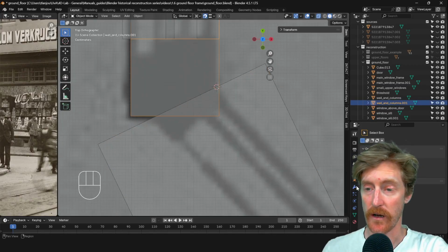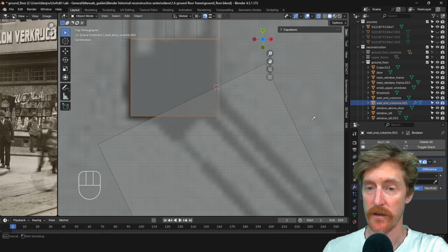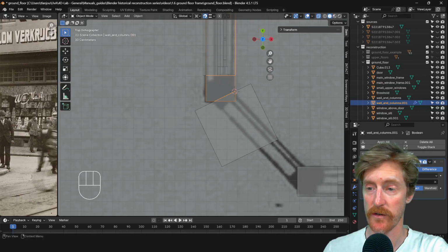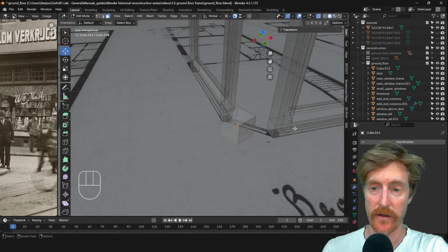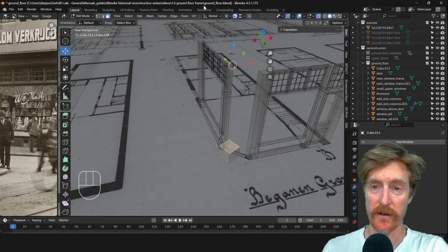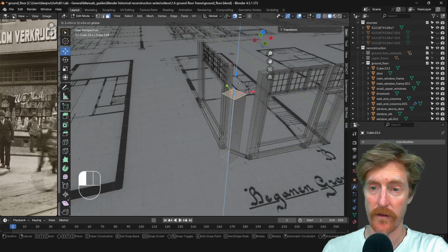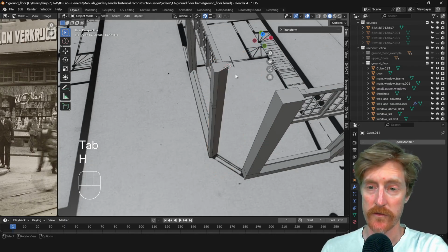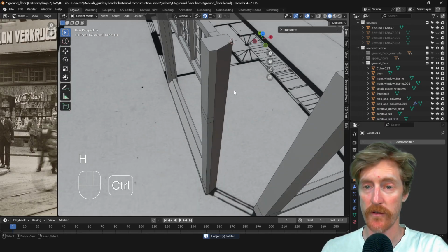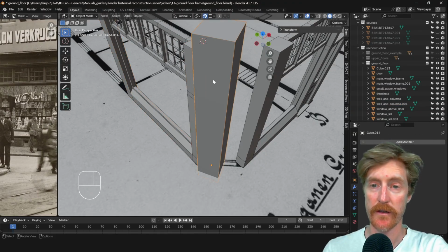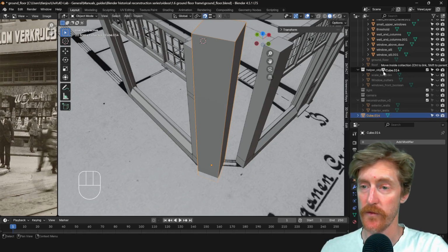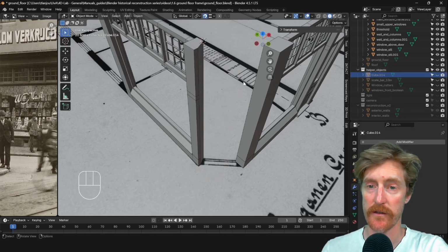And then I'm picking the modifier and generate Boolean. And I use this. And let's see, I hope I select the right one, this cube. And then, oh, the cube isn't high enough, so I have to make sure that it cuts over the entire length. Just see if it worked out well. That looks good. What we can do now right away is go here and apply the Boolean. I could just move this to the helper objects, hide it.